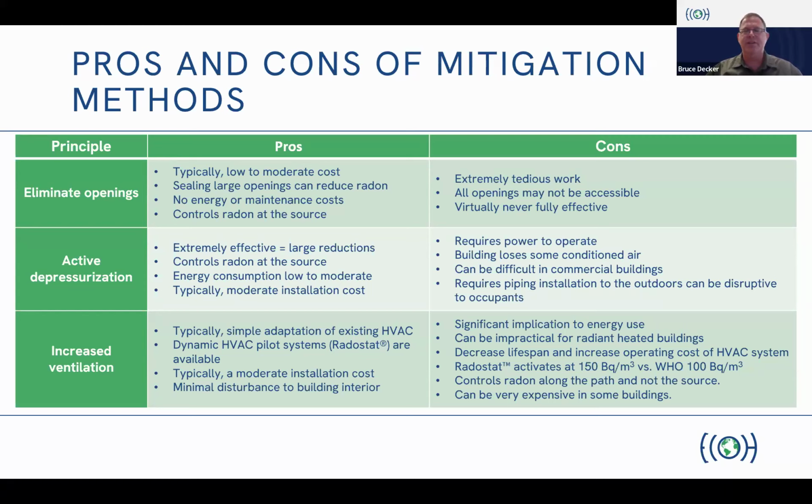Active depressurization, let me explain what that's about. It's extremely effective. We see 90 to 95% reductions 80 to 90% of the time. So incredibly effective. Controls radon at the source, so it never gets in the building. Your workers or your occupants aren't overexposed. That's great. It's just like a fume hood, right?